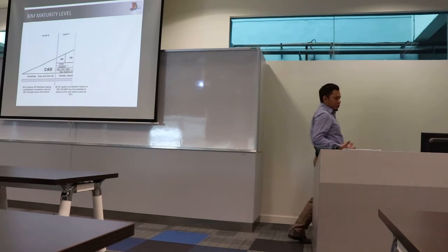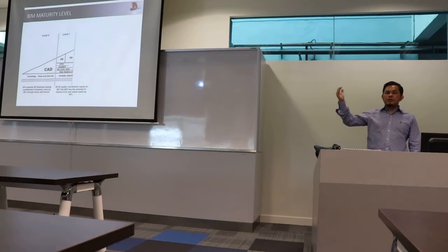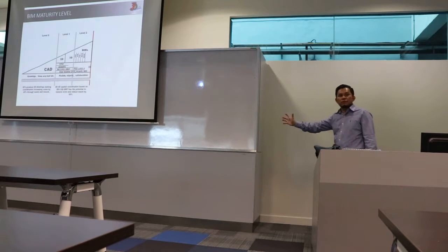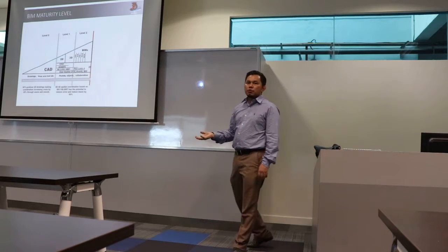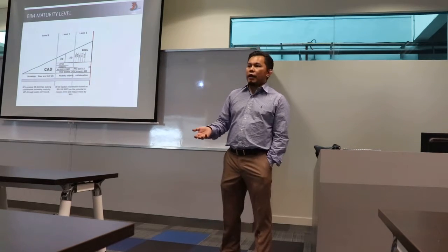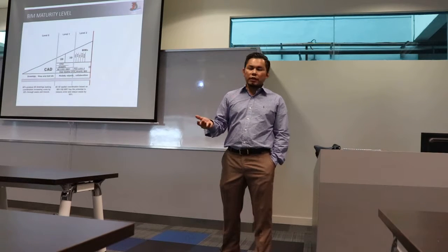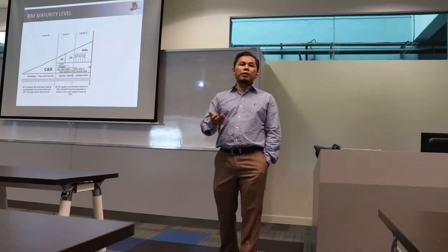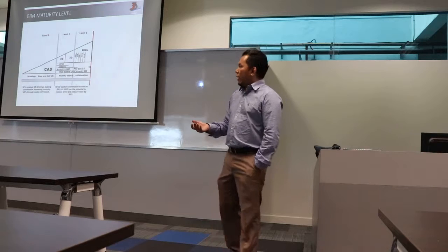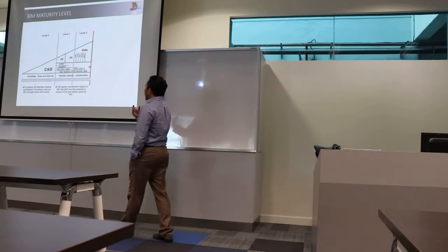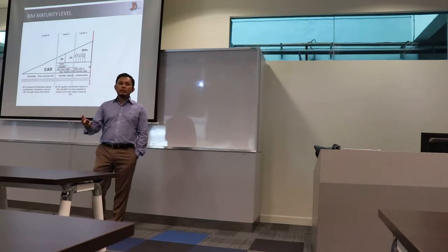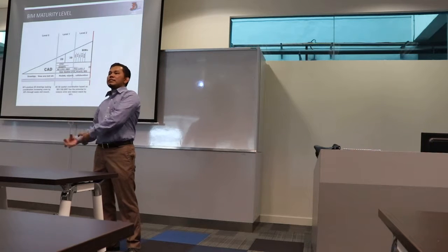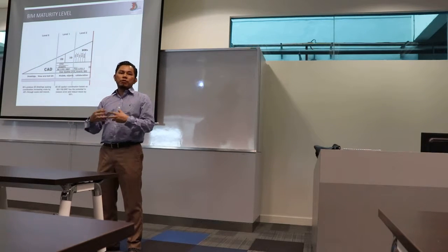Now, currently in Malaysia, if you are talking to organizations such as Gamuda, UEM, IJM, everybody is talking about BIM level 2. So what is BIM level 2? BIM level 2 is about having BIM processes that you can do by leveraging on the CDE, which is the Common Data Environment. The Common Data Environment requires you to have a system that monitors all the information that goes in and out. It doesn't mean that everybody is looking at the same information. It's just that the information is all related.